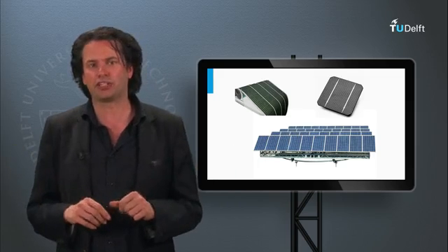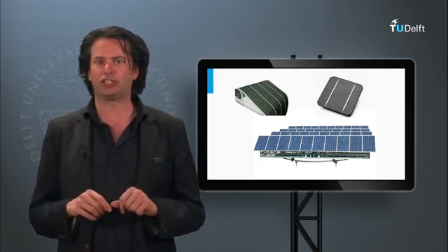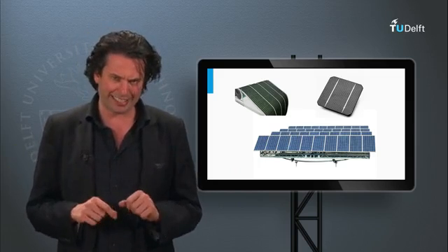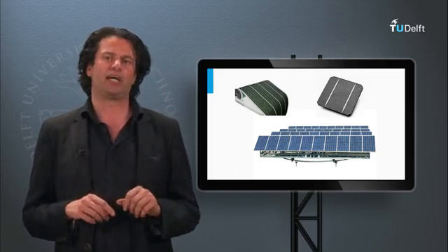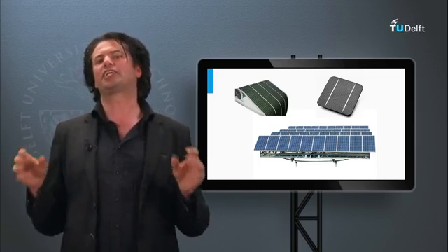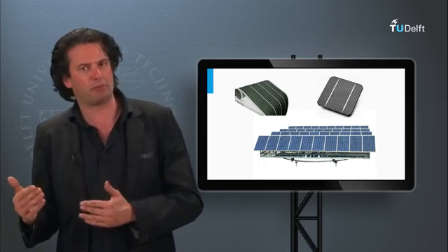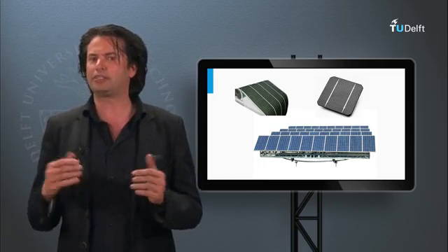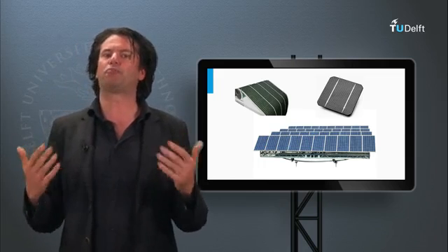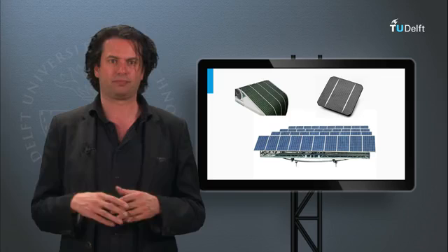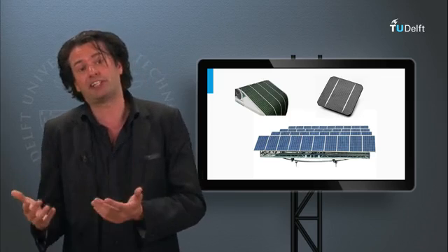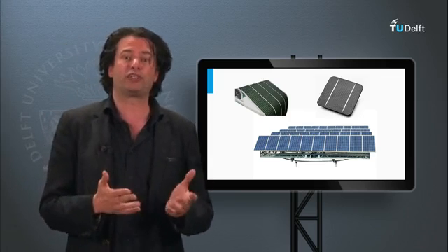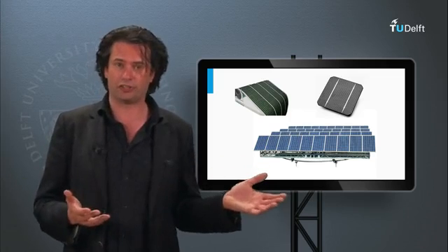More PV technologies are being analyzed at the Delft University to understand the extent of the temperature effects. As said before, the amorphous silicon technology shows very low temperature coefficients due to their high open circuit voltage. This means they would show a better response under high temperatures. However, their efficiencies are far lower compared to some of the best crystalline silicon technologies.